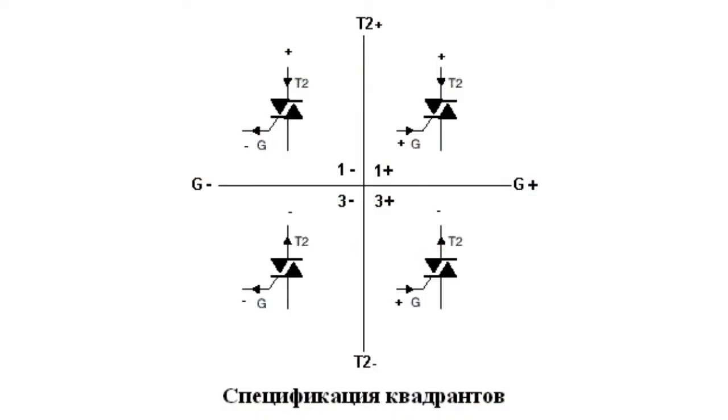The difference between a 3-quadrant or 3Q triac and a 4Q triac lies in the non-critical structure of gate overlapping. This doesn't allow carrying out control functions in the 3 plus quadrant. However, it also excludes the possibility of malfunction and helps avoid many problems associated with 4Q triacs. Firstly, 3Q triacs have better performance capabilities. Secondly, in most cases it is possible to do without a choke and a damping chain.